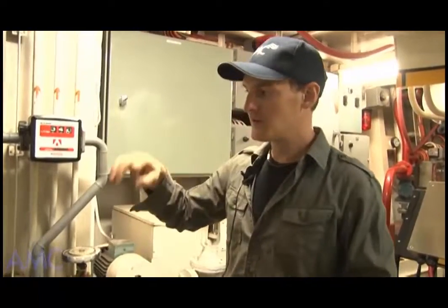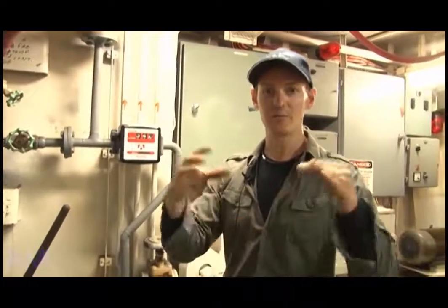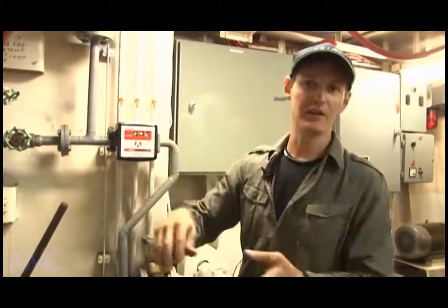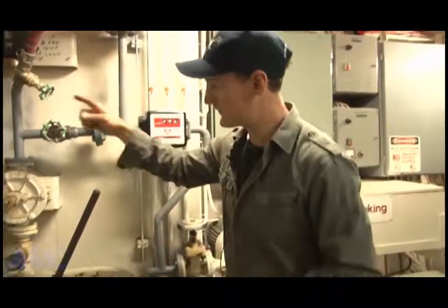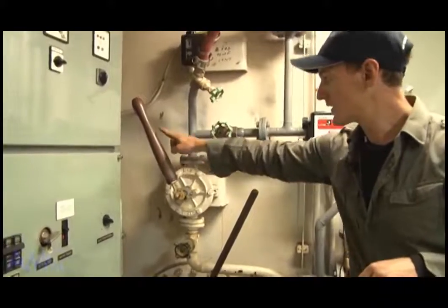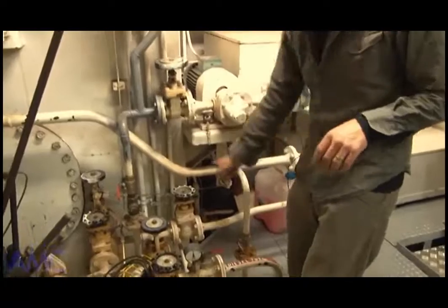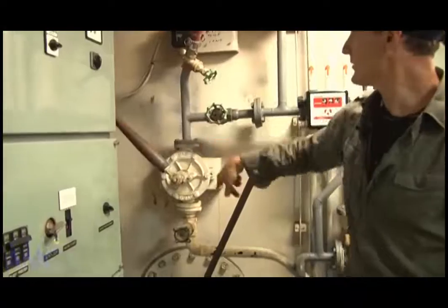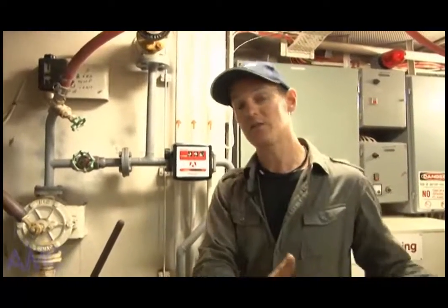If all else fails, if we end up running out of fuel and we lose all suction and we black out, we can't start an engine because we don't have fuel in the day tank, then survey requirements are that we've got to be able to pump it manually by hand. So in that instance we've also got a hand pump. It's the same suction line from our bunker tanks, but it's using a semi-rotary hand pump that we can then use to pump up our day tank and then get a start on one of our engines.